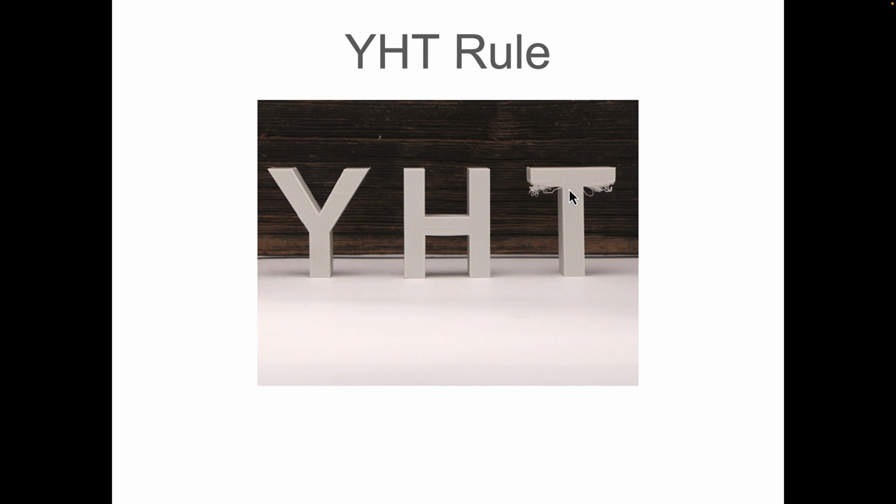And with this T, there's a few ways you can approach it. You can either lay it flat here, like turning it upside down and allow it to lay flat on this side, or you can just lay it flat on its side. Say if I push the T back and it's just flat that way. So you've got options before you resort to supports. Because supports take time and use more material, so if you don't have to use them, don't.